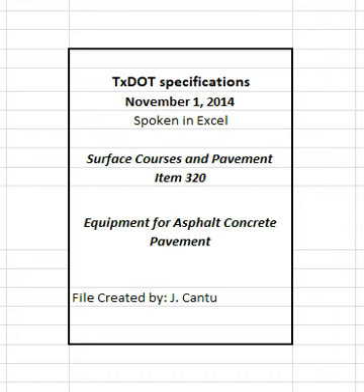2.3.5 Thermal imaging system or handheld thermal camera. Provide a thermal imaging system or handheld thermal camera meeting the requirements of TEX 244F. 2.3.6 Rollers. Provide rollers meeting the requirements of item 210, rolling, for each type of roller required for compaction. 2.3.7 Straight edges and templates. Furnish 10 feet straight edges and other templates as required or approved.